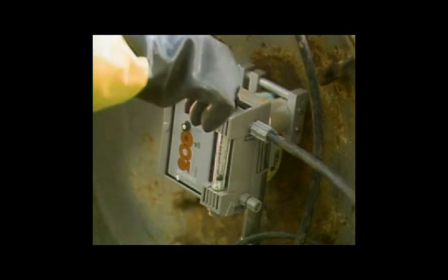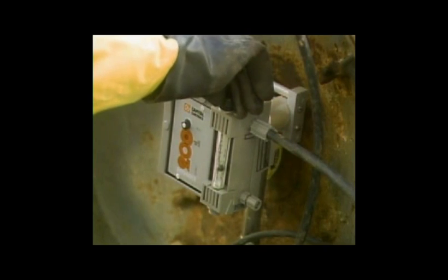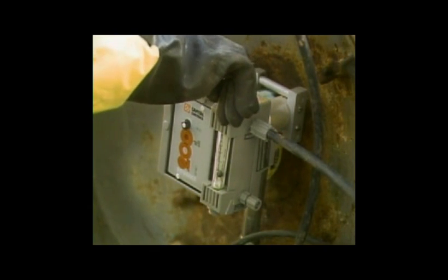Microorganisms can be controlled by adding chemicals called biocides. Chlorine is one biocide that's commonly added to water to prevent slime growths. Chemicals are added to the water in cooling towers for many reasons. You may be responsible for adding chemicals to the water, so you need to know how to do it safely.